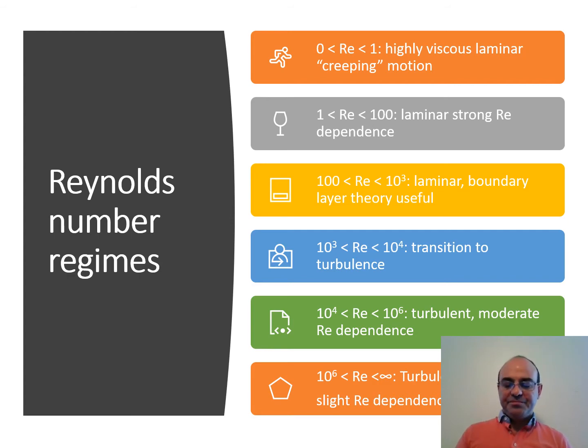When we have a fluid flow next to a solid wall, that solid wall is called a boundary. Very close to the boundary, the viscous effects are important. Far from the boundary, the viscous effects become less significant. So the boundary layer means the layer of fluid which is under the effect of viscosity, and it is very thin and close to the boundary, for instance the walls of the pipe.